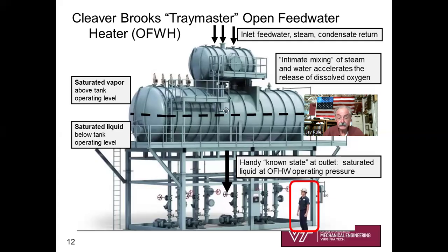Okay, just huge. And so the arrows going in, that's going to be the inlet feed water, steam, and condensate returned from other heating sources that you may be using. A little bit more on that later. But the neat thing is what's coming out of the bottom of the tank is saturated liquid going off to the feed water pump.